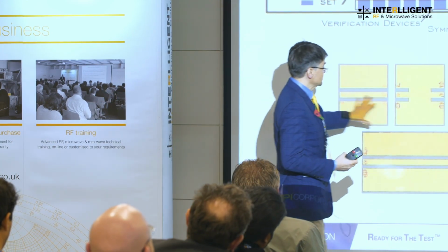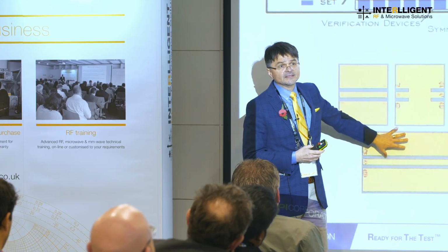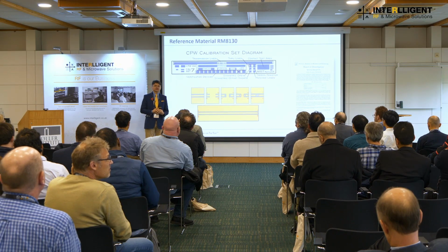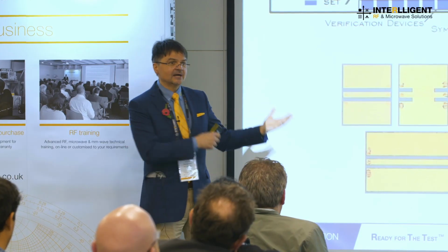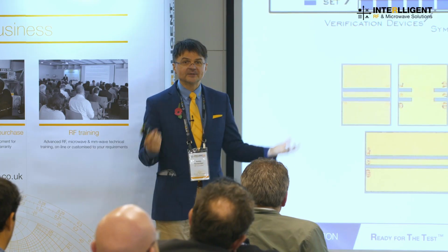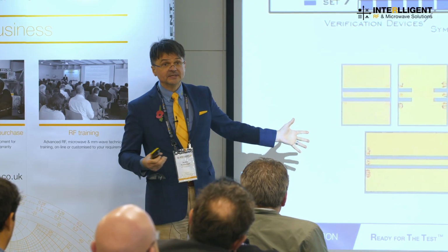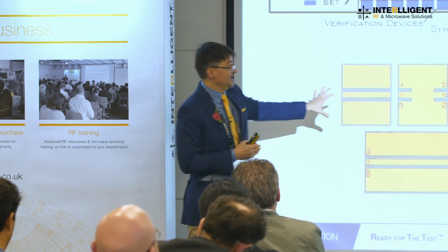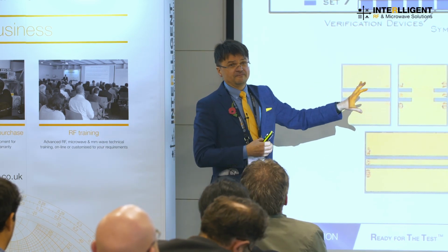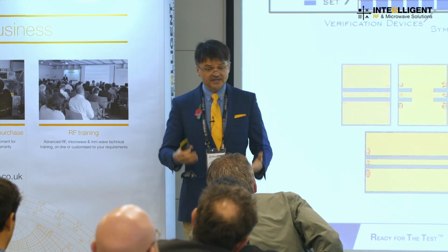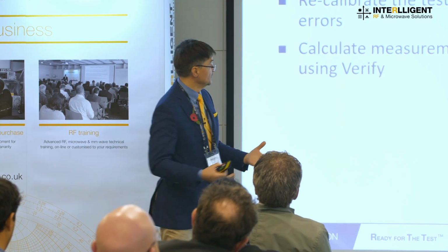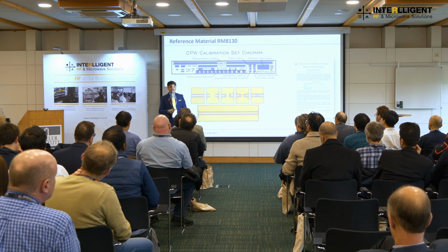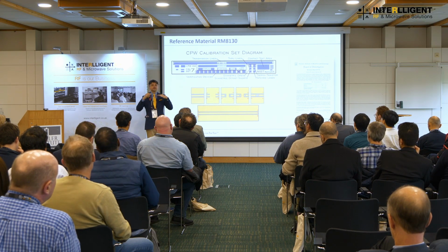And it was a very interesting story with that. Actually, once we had this reference material in the past, we didn't know how to use it. We ordered it. At that time, I worked for Zeus Microtech as an RF application engineer, and I read about this possibility, and I really wanted to link my setup with the NIST setup. We ordered this device, this RM8130, which was very expensive. When we received it, and after I put it under the microscope, I saw that my devices were scratched already. There are some footprints from the probes.